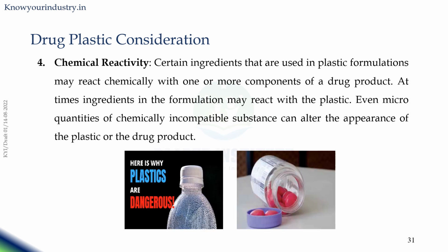Chemical reactivity. Certain ingredients used in plastic formulations may react chemically with one or more components of a drug product. At times, ingredients in the formulations may react with the plastic. Even micro quantities of a chemically incompatible substance can alter the appearance of the plastic or the drug product.